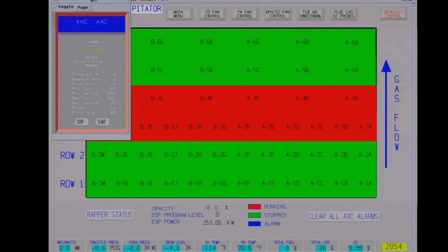On this other screen, we have our precipitator running. We just have 2 rows, 3 and 4. The front rows have 2 TR sets, transformer rectifier sets, putting about 50,000 volts out to the plates to knock out any particulate. Most of your ash is dropped out in the first 2 rows. The back rows are more for just cleaning up anything that gets through the first rows. So we'll start up with row 3 and row 4 for startup.